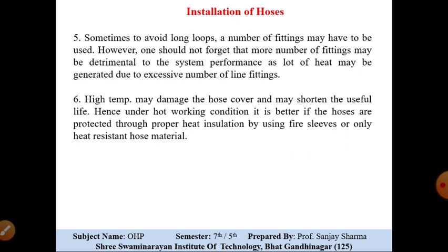So it's very important that the temperature of the fluid should be under control, and the material we use for the hose should be extraordinary heat resistant material, or it should be properly heat insulated, or else it will damage your hose pipe and create an accident.